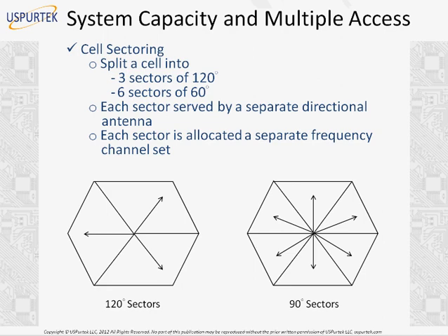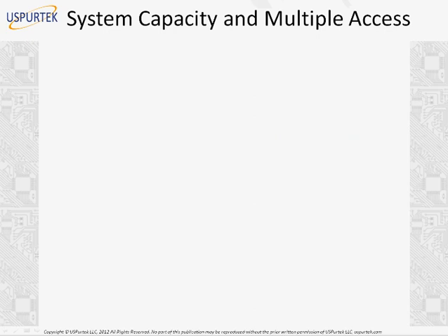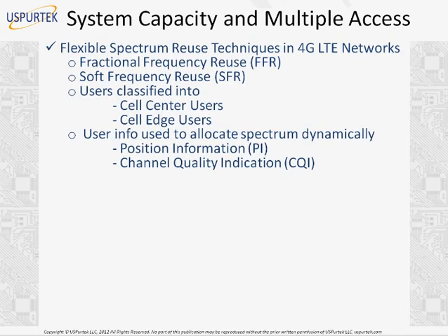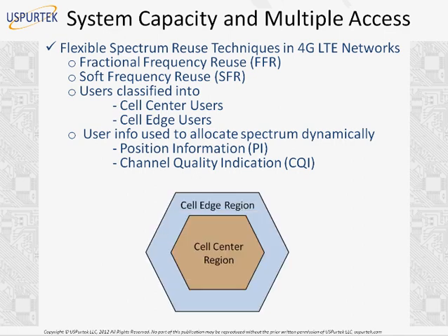So there's another question: the co-channel user ratio remains the same. Okay, yeah, that depends on how big your size is. It's a very intelligent answer from Joseph, that of course, if you're not reducing the cell size, your D by R ratio remains the same. And if you're not changing it, what is the value of N you're keeping here? N is equal to 4 or 7 or what? Okay, very good. Let's move forward to the next slide.